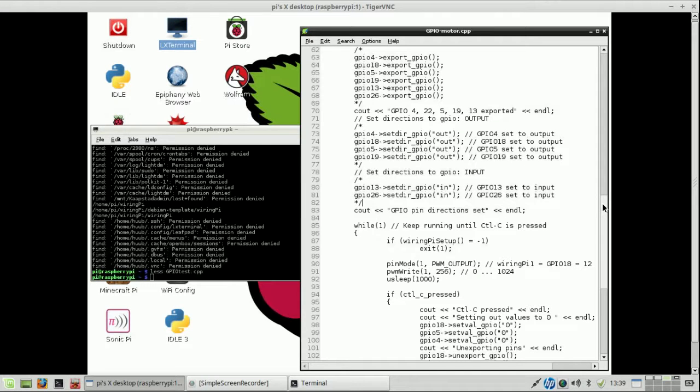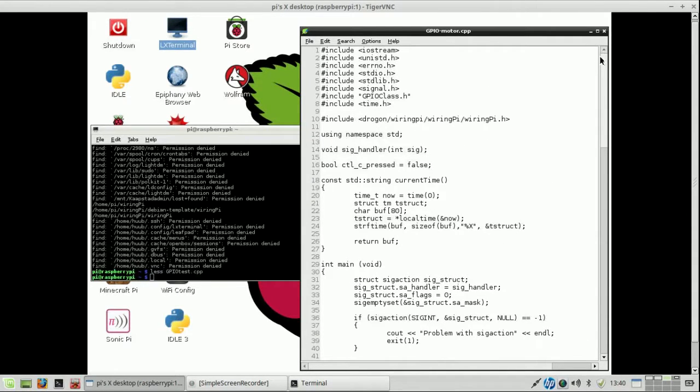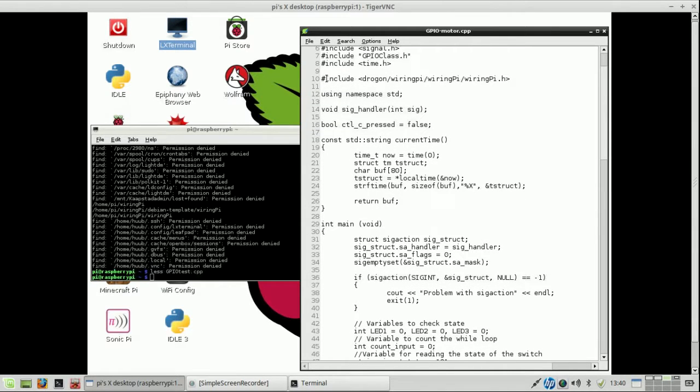Some further research led me to the conclusion that I haven't been using the exact right approach, because of course you need a transistor like I have done with my Arduino, but also, and I should have realized that a little bit earlier, pulse width modulation. The motors I'm using are from Fischertechnik, and they use pulse width modulation. So I've been looking for the same thing on Raspberry Pi, which is there, which I didn't know, and the pulse width modulation is on a few pins, only a few.